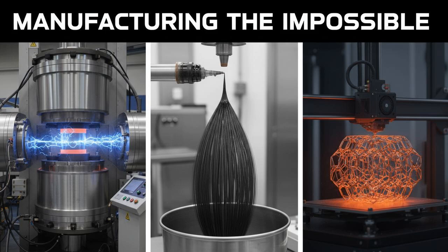Another method involves polymer-derived ceramics. If you want to make a ceramic fiber, you start with a liquid polymer, essentially a plastic, spin it into a fiber, and then burn the organic parts away in an oxygen-free furnace. The carbon and silicon backbones rearrange into ceramic SiC fibers. This is how we create the reinforcing fibers for jet engines.